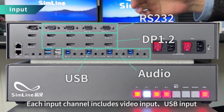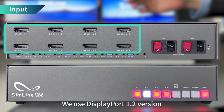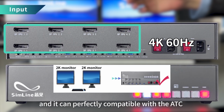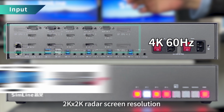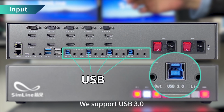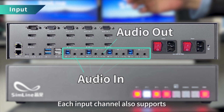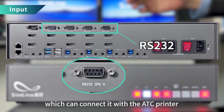Each input channel includes video input, USB input, audio input, and RS-232 input. For video input, we use DisplayPort 1.2, which supports up to 4K 60 resolution and is perfectly compatible with the ATC 2K by 2K radar screen resolution. For USB input, we support USB 3.0 with up to 5G bandwidth. Each input channel also supports analog audio input and output. And each channel also supports a full-pin RS-232, which can connect to the ATC printer.